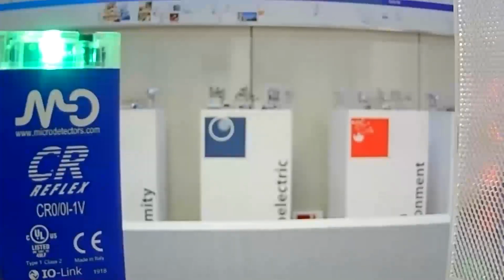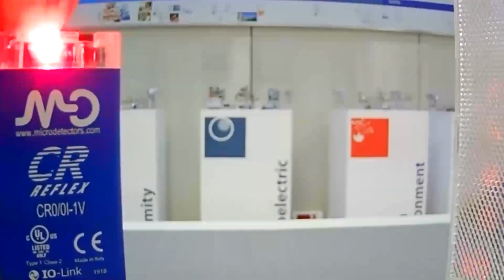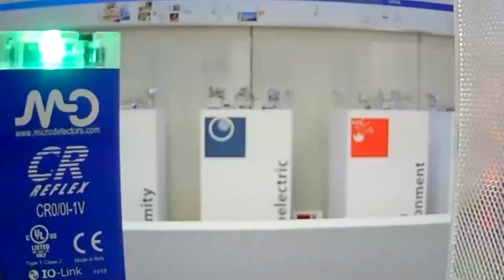Okay, thank you. Today we see how to teach a standard sensor, a CR0, by the teaching buttons that you find on the top of the sensor. The first teach method that I want to show you is the standard teaching. So please check the LED on the top. I just push the button for a couple of seconds. And now we have taught the sensor in a very easy way.